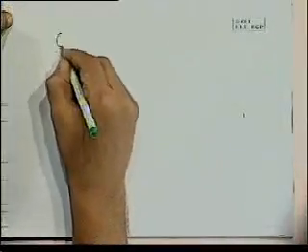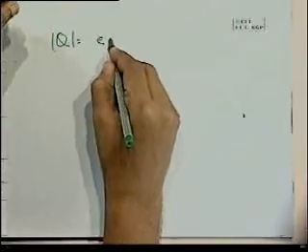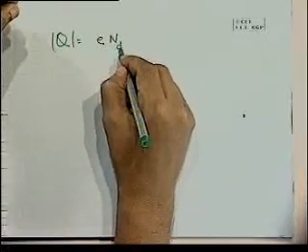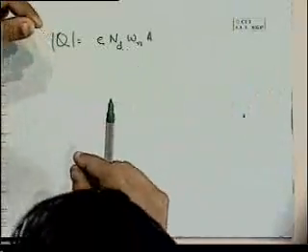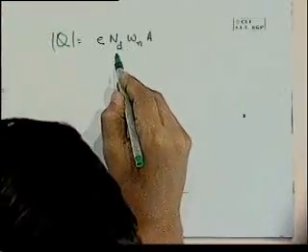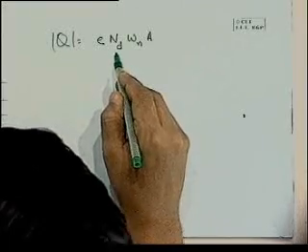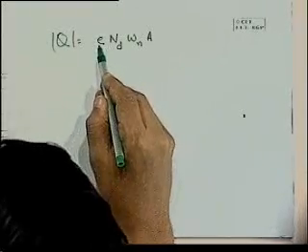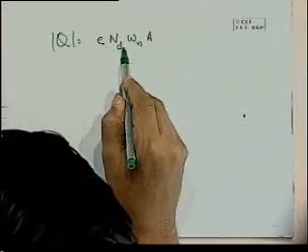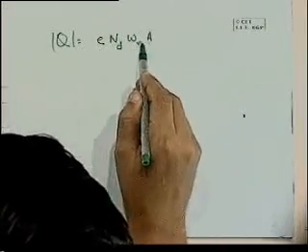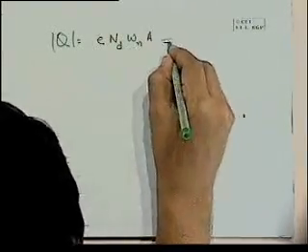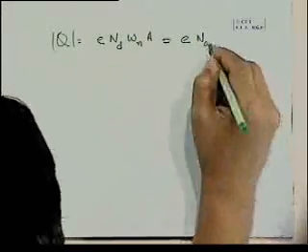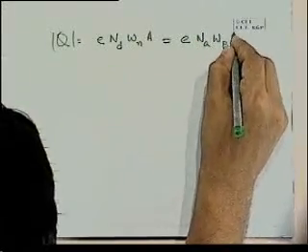Earlier we saw that the charge stored in the depletion layer on either side of the junction could be expressed as Q equals e Nd Wn A. I had left out the A because I said area is the same on both sides. If you remember, Nd is donor concentration, how many per centimeter cubed, and when you multiply it by e, you get the charge per centimeter cubed multiplied by a volume, which is the area times the thickness of the depletion layer, which is also the same on the other side, e Na Wp A, and the area is the same.